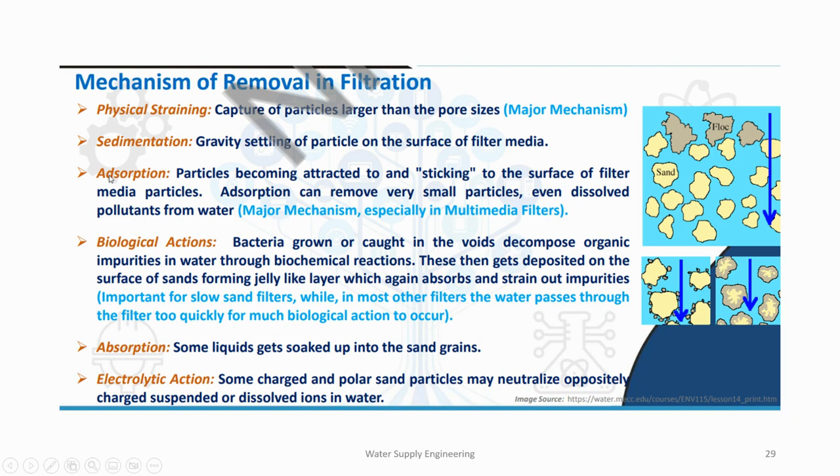In the case of adsorption, the particles stick on the surface of filter media, and this is a major mechanism, especially in multimedia filters. This process can remove even dissolved particles or dissolved pollutants.